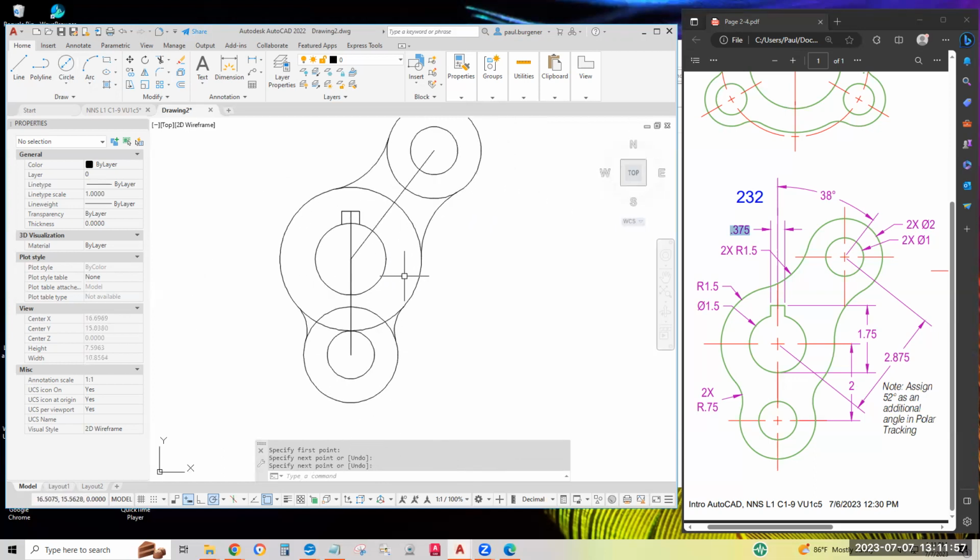From here on, it's just erasing and trimming to whittle down the drawing to just the green lines shown here. So, we can quickly erase a few lines here. 1, 2, 3 lines. Remember, this is 2 lines shown here. One for the top keyway and one to go to the bottom. Let's go to erase, select all 3 lines with a crossing window. Command prompt shows 3 objects are found. That's all we want to erase. Hit enter or space bar.